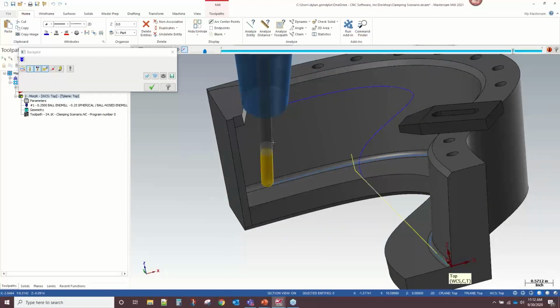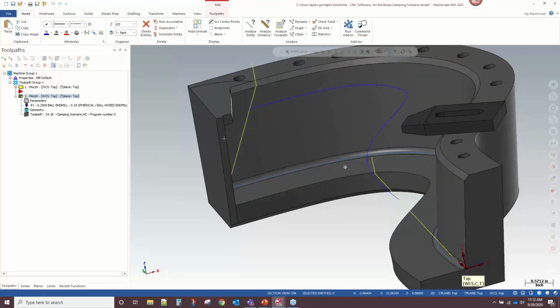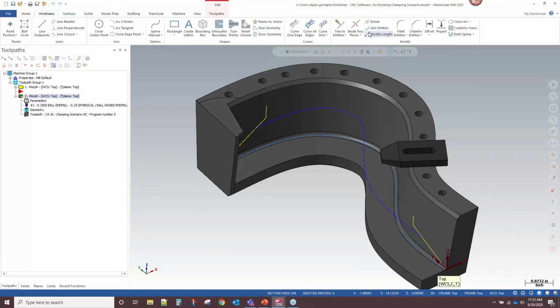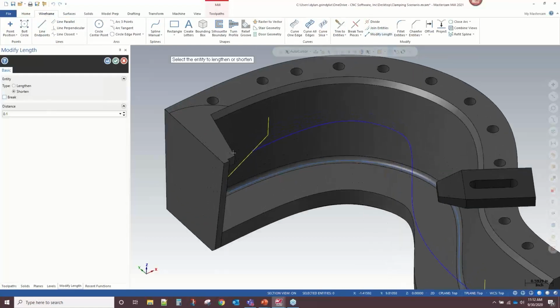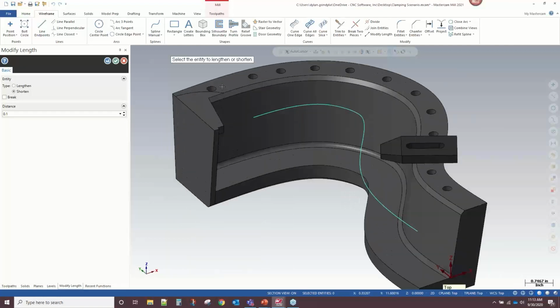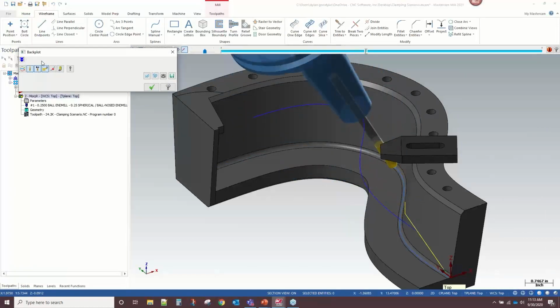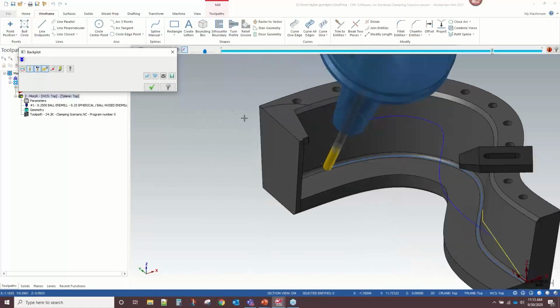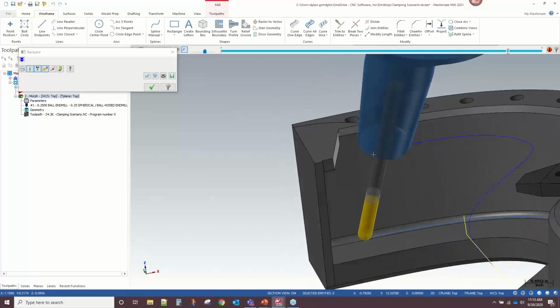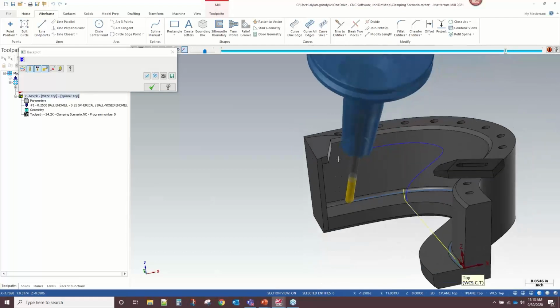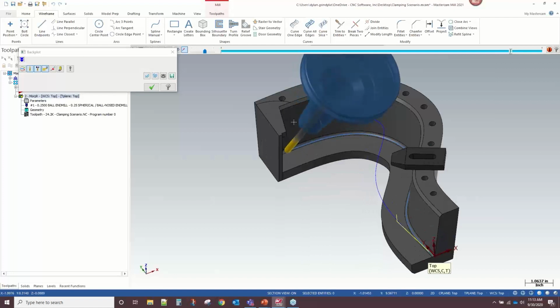And if this sweep looks too abrupt, if we're feathering too abruptly, I can simply modify my chain to modify the motion I get. So I could say I'm going to shorten my tool axis control chain. I shortened it about 1/2 inch. Let me regenerate that. And because I always have to be pointed along that chain, what happens when I reach the end of it here is I'm still pointing at the end and I'm feathering out the path along a greater distance. So I don't get such abrupt tilt motion right at the edge of that overhang.